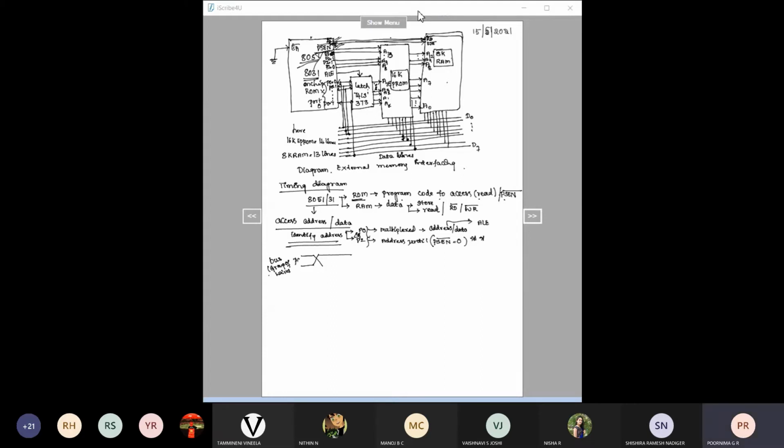See, port 0 is holding the data or address. How many bit bus pins you have connected to port 0? 8, ma'am. 8. So these 8 pins I am representing as port 0, which is nothing but port 0.0 to port 0.7. All these 8 individual pins, when I combine, this is the structure we are going to make use of.